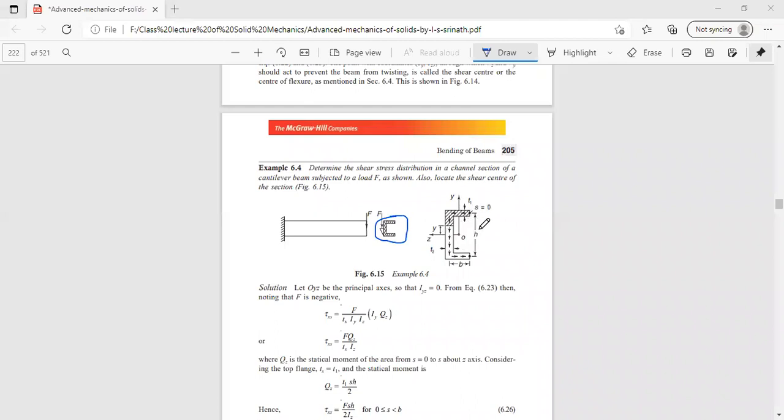And what we have here is the length of the channel, measured not from the ends but more or less from the center of both the flanges, equal to h. And the length of this channel along its curvature is given as s equal to 0 at this point and equal to s at this point, as we have discussed for a curved beam.